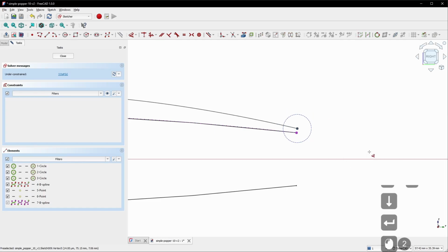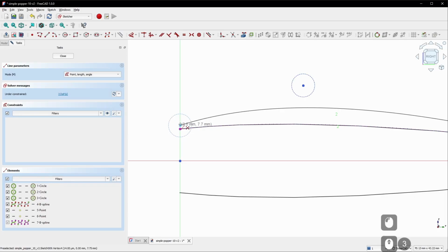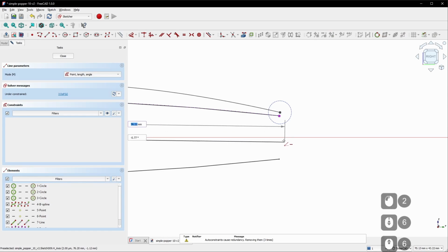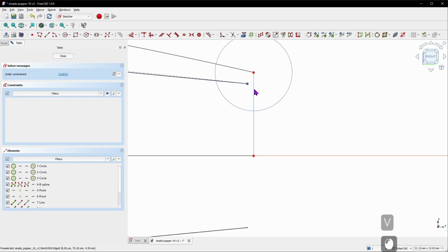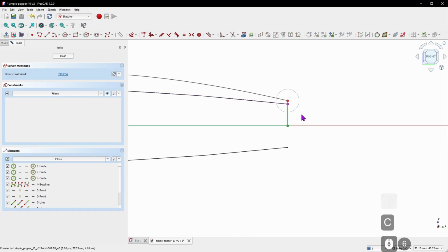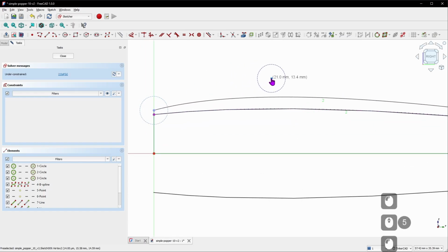Now, because our lure is a very simple circular shape, we can just perform a revolve. So I'm going to close the sketch with some straight lines coming from that B-spline down to the origin, and the origin over here on the axis, and then connect up to our B-spline. I'll make this line vertical, and I'll select this point from our side profile and the line and make a coincidence constraint.